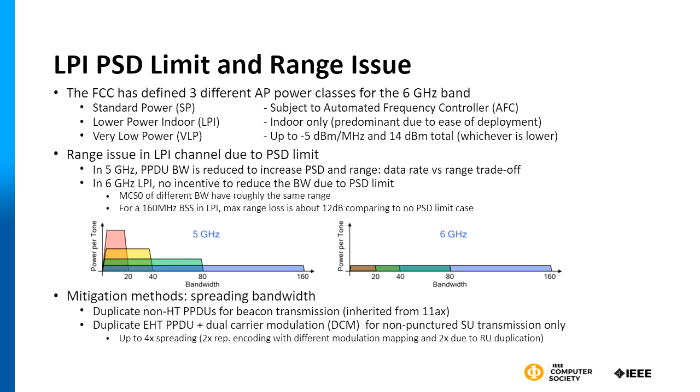Okay, awesome. And then another question is more about the puncturing. When puncturing gets modified, does the station need to reassociate again? Is CSA required? No, so essentially, I'm assuming it's being discussed about static puncturing. The beacons contain these punctured bitmaps that the stations receive every time they receive the beacon.